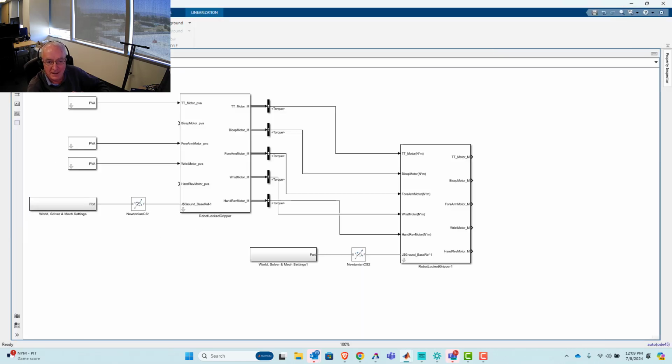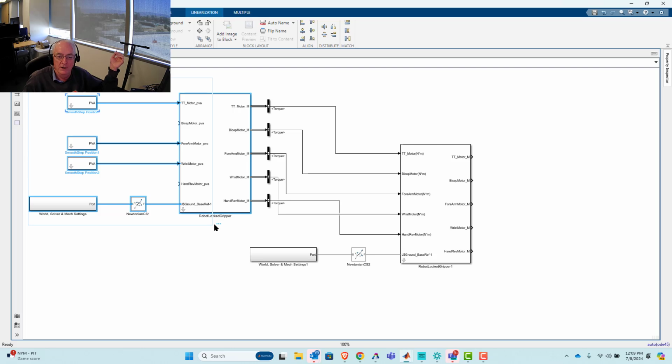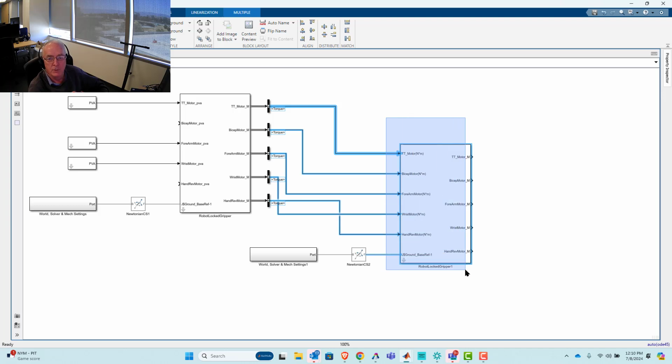Even in a computer simulation like this, where presumably we have perfect information, well, we don't. It's the numerical error, probably on the order of 10 to the minus 16th, that will build up in an unstable system and lead to a departure between what we think is happening with our prescribed motion robot and what's really happening with what I'll call our forward dynamics robot.